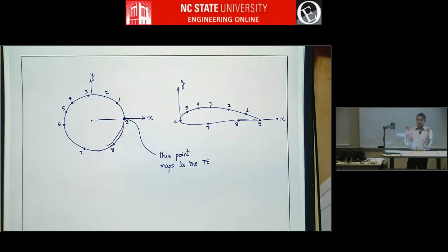So these are just ways to divide the airfoil into some regions, and in each region you'll go and say, this is the velocity distribution I want at this condition. So don't think that just because you use 4 segments, which is the minimum number of segments you have to have, it will be a bad airfoil or a jagged airfoil or something. It's not at all like fitting a spline through a few points. If you have 4 points and fit a spline, it will look really bad. It's not like that. You're not fitting a curve through these points.